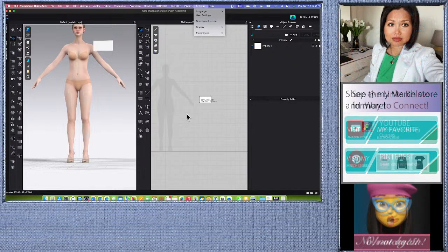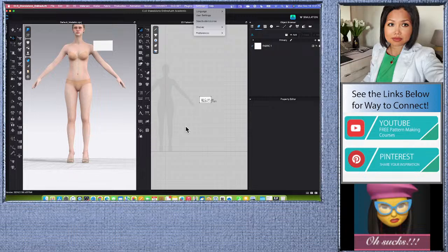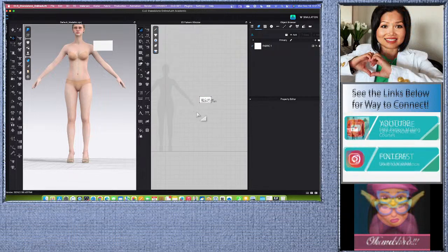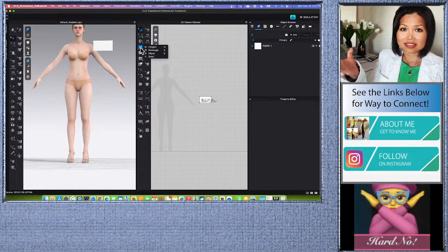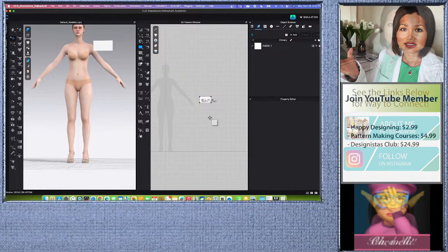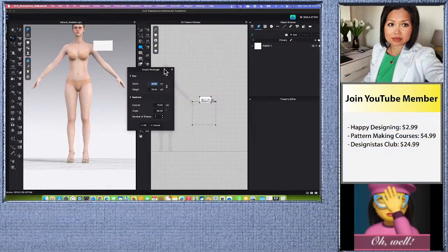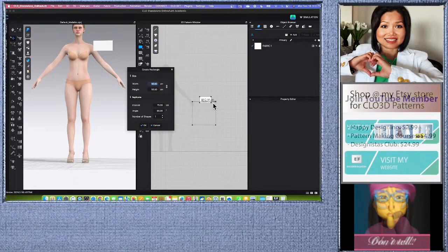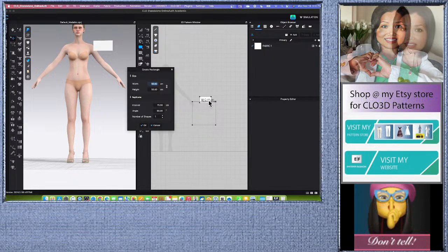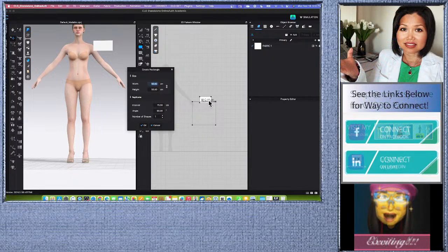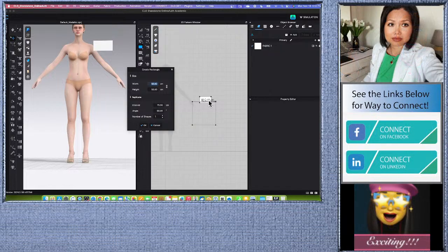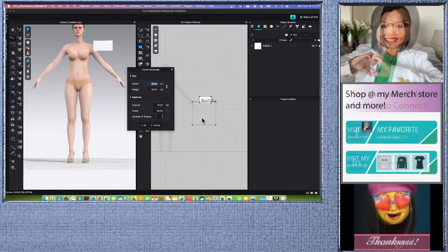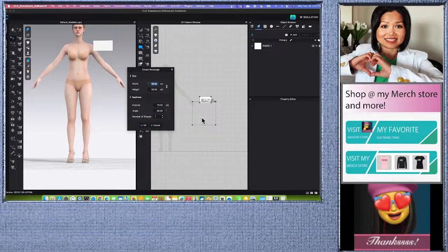Okay, so here now we're gonna create this skirt. So we will use the rectangle tool here, and I'm going to click one on a page because we want to type exact measurement. Okay, first of all, my measurement here is 64. So 64, if I divide it by 4, because we want to measure and then turn it to 1/4.